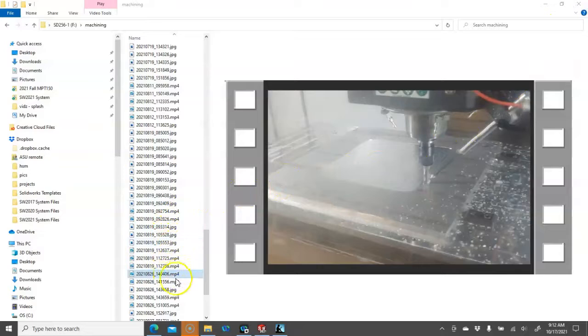So surface finish then are these small grooves that are produced by an epicycle of the tool spinning and moving in a linear direction. And the tool has variation, the machine has variation, loading, unloading. So the waviness becomes these lines where the tool overlaps. A larger tool on a machine where the head is trammed well will produce a flatter section, and these waviness lines will get a little bit further apart. So let's see if the pictures are here.